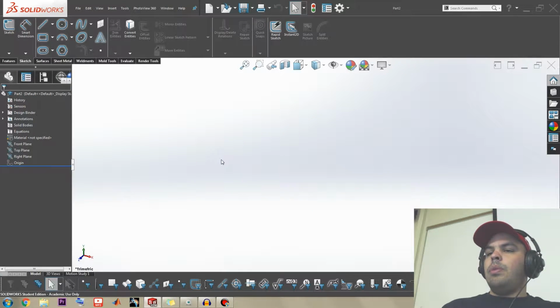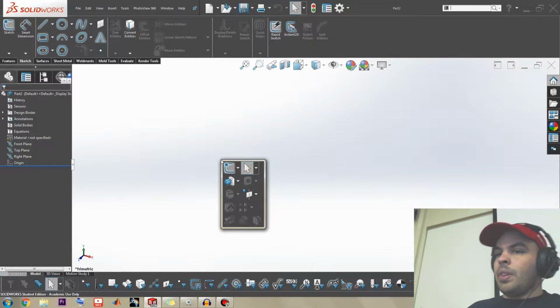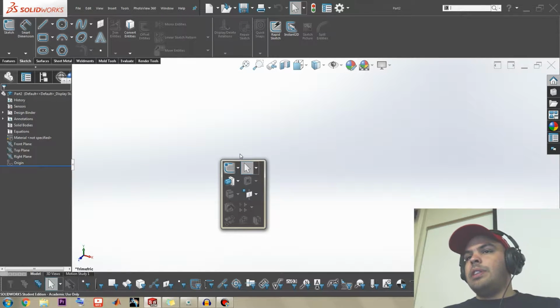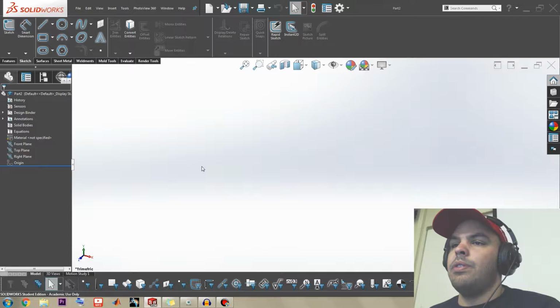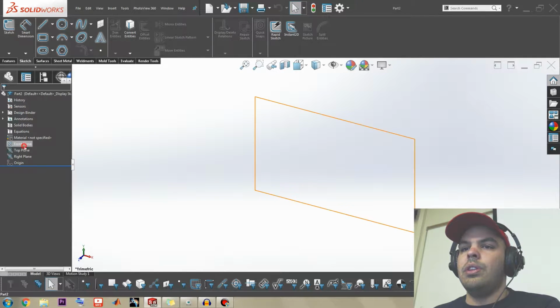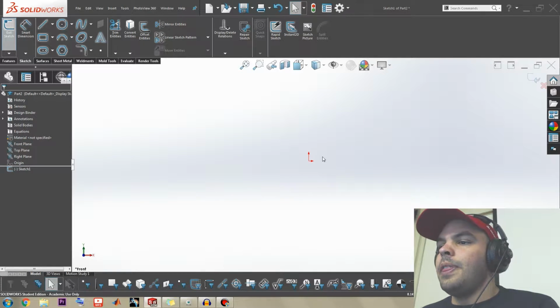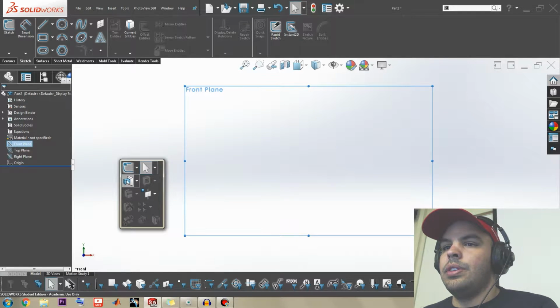One of the nuances is that he uses the S key to bring the super shortcut up. When you press this key, it's already loaded with some goodies for you to pick from, but the one that I added in, and yes, you can add stuff in the menus, is begin sketch right on the S key, so you can use that to your advantage. So you can click front, new, and then you have that. And actually, let's set this to millimeters, front, like that.